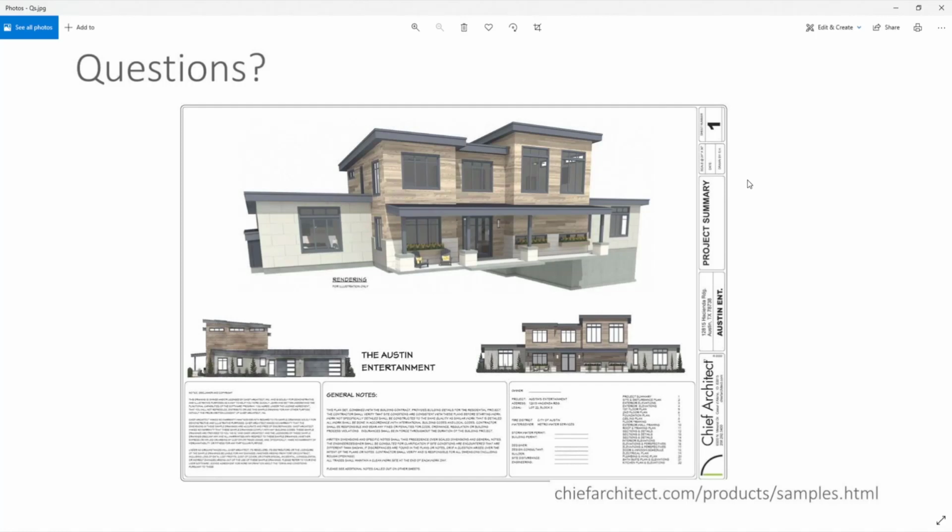Well, I observed that when you made the shed roof change on the existing plan that you're working with, you initially made the walls treated as a gable roof, and then you clicked on the walls to turn them into shed roofs, and that raised up the higher side of the shed. And I didn't know if that was an automatic feature that accounted for something that I wasn't accounting for by simply dragging the wall up and then putting on a manually defined shed roof. I did not do any wall editing on this model.